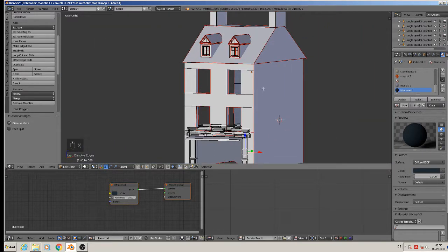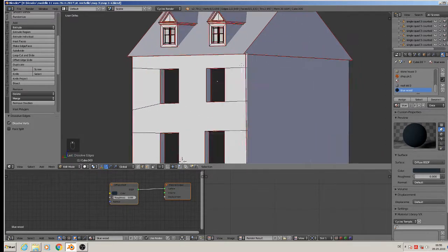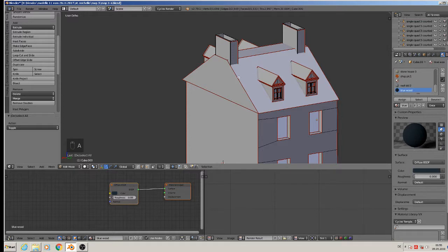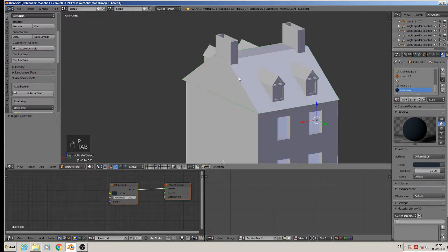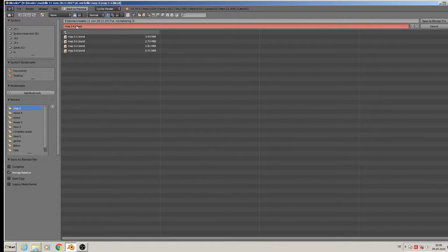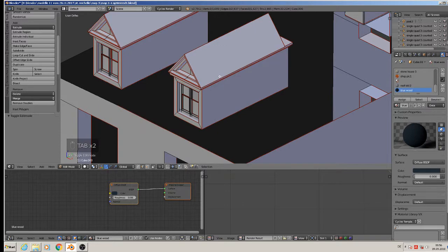So, look around. The base mesh seems nearly okay, only here's some weird stuff. So because of that we now mark the roof, press P to separate the selection, and now we move that roof to the 6th layer, so we have space there to see more. File, save as, we call it last version number optimized, optimized 1. Save.